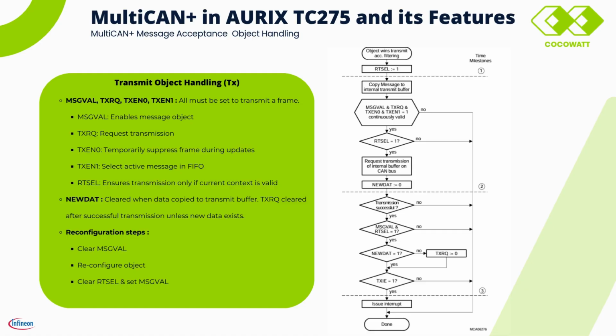Next, TX enable 0. It is particularly interesting. It allows us to temporarily suppress a frame during updates. This provides flexibility and control over the transmission process. Finally, RTSEL ensures that transmission occurs only if the current context is valid, preventing errors and maintaining data integrity.